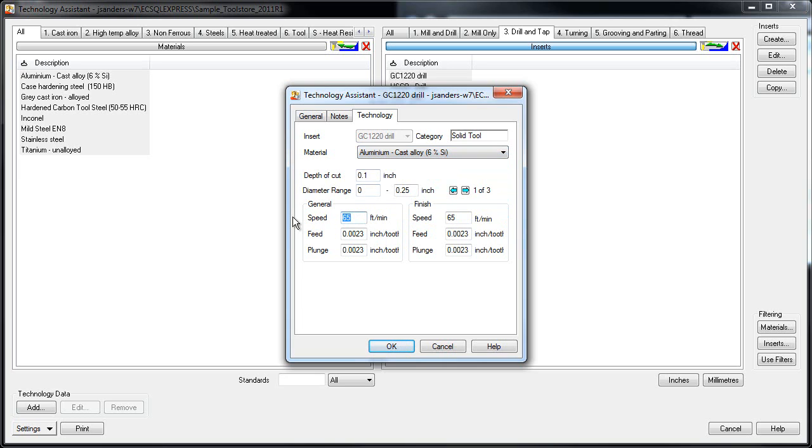In this case, I'll enter unique data for the aluminum material. Notice that the size ranges are already set up. All that I have to do is change the value within the size range. Now once you've entered values, the changes are done immediately and are available for tool lookup within EdgeCam.